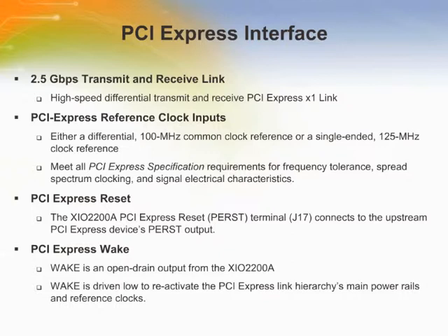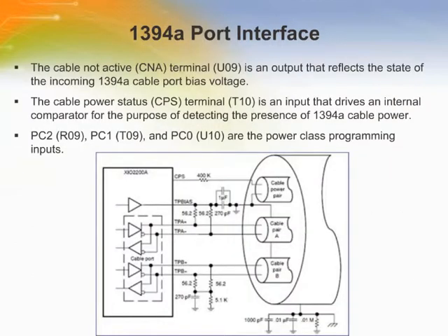The XIO2200A PCI Express reset terminal connects to the upstream PCI Express device's PERST output. The bridge also supports a PCI Express sideband wake feature. The device has two 1394 cable ports that operate at 100, 200, and 400 megabits per second. These ports are compliant with the IEEE standard 1394A2000 Amendment 1.